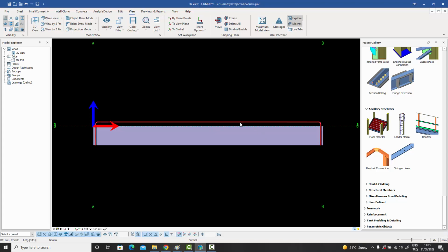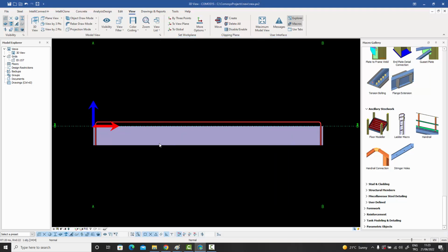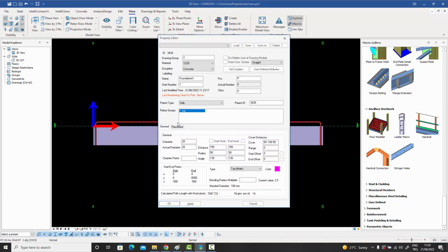Now, one thing which needs to be said is that in the simple cases which are convex, we will usually see that the positive numbers would mean going inside the concrete and negative numbers would mean going outside the concrete. But sometimes the bars can be cranked, or they can be concave, or they can be of a nature in which the local directions might switch. So it might be that you might have to give a minus sign or a positive sign depending on the shape of the bar. But either way, you should be able to get the result which you want. So let's now bring this back to 50 and move on to the next variable.